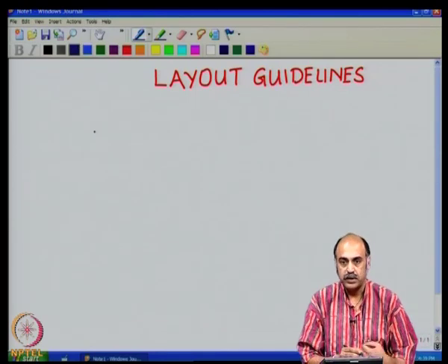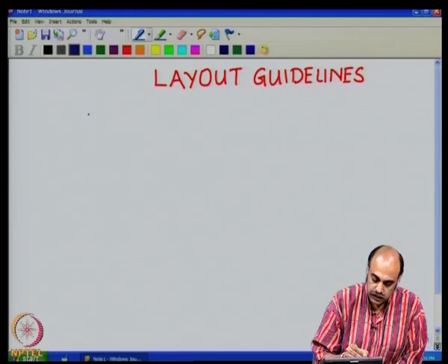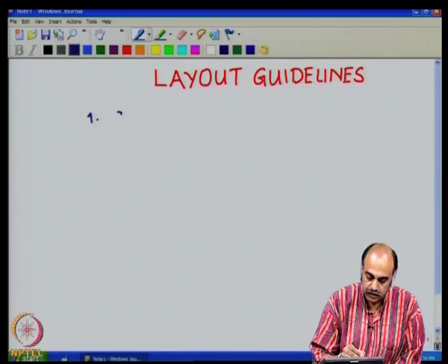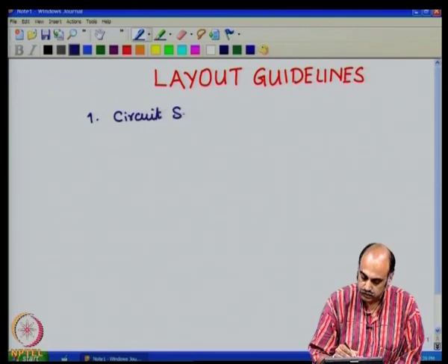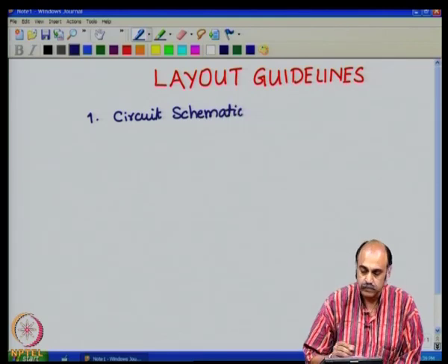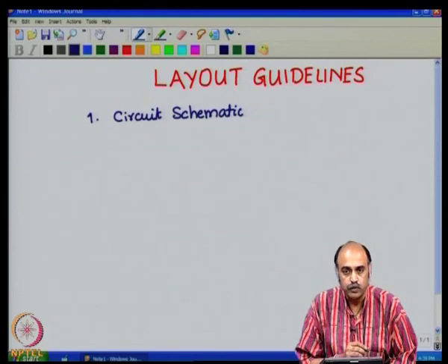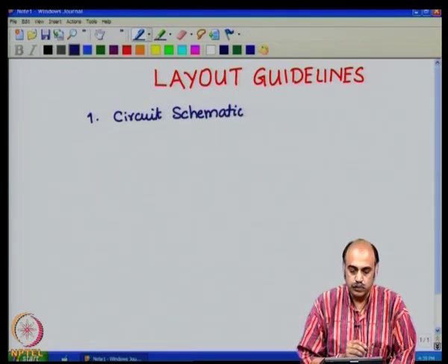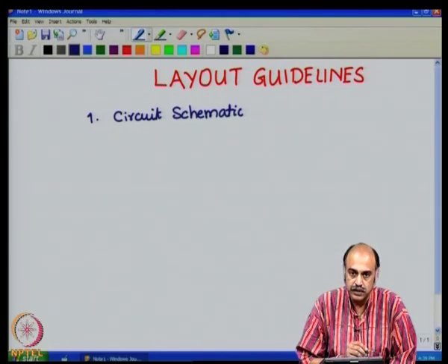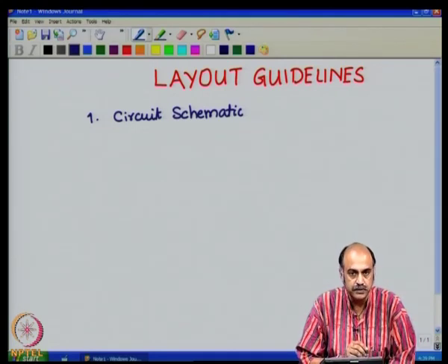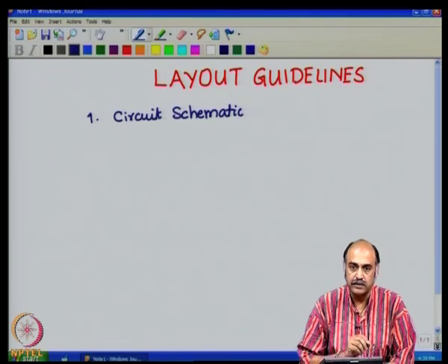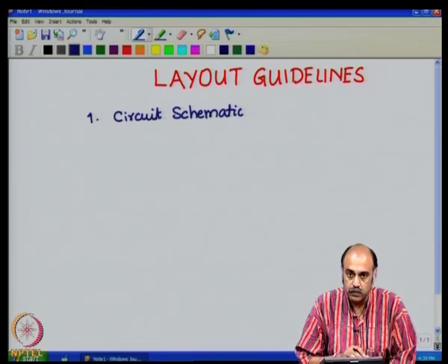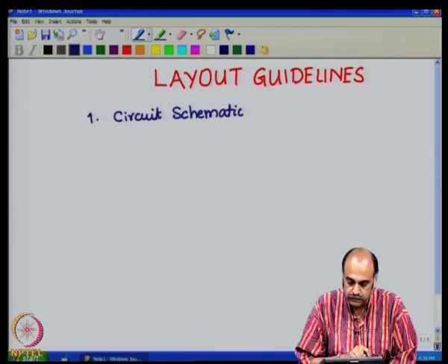If you are making a printed wiring board, the first thing that you would do is have a circuit schematic. Now, the circuit schematic is the culmination of your paper design exercise. You would have thoroughly analyzed the circuit, designed the circuit on paper, maybe even simulated the circuit, and after having done that, you have frozen the circuit and the values of the various components.